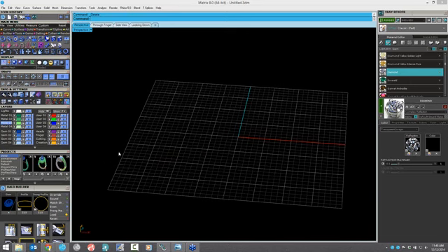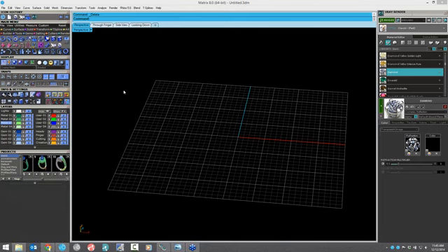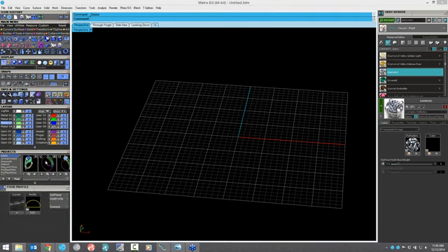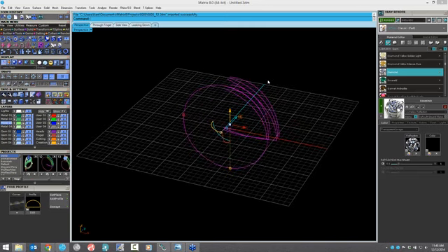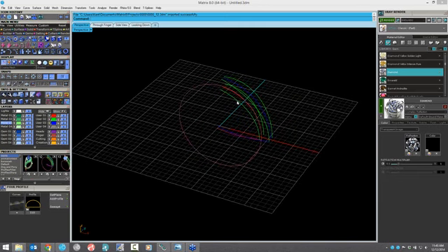Now I want to talk about another new function called Sweep 4. We have Sweep 1, we have Sweep 2, and we're going to skip 3 and head right to 4. Let me call up a job bag here. Here's the setup that I have. I have 2 red curves that, with curve from 2 views, make these 2 green curves. And then I have this blue curve and this blue curve, and the curve from 2 views makes those.